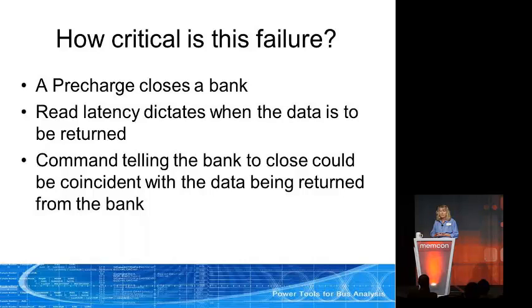In the past, what engineers used to do was hook up a logic analyzer and look for one violation at a time. Okay, and that was obviously extremely laborious. Every bank, every rank, every violation, how long would you let it run? What type of software would you be running? Would you be voltage margining? Would you be in a temperature chamber?